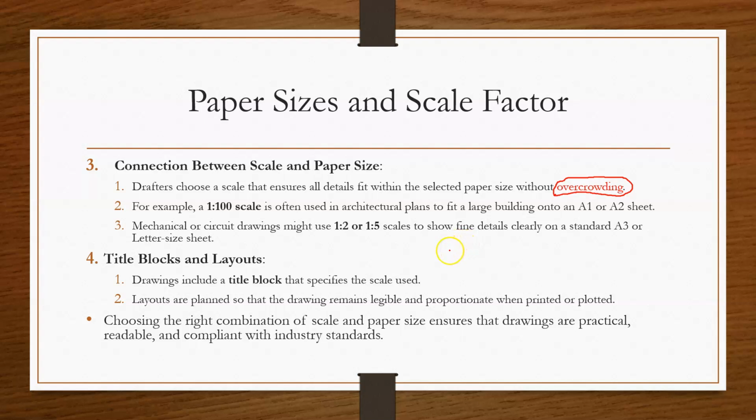Now that is also going to be where you're going to see the "not to scale" or the actual scale factor or anything of that nature sitting there. And I already kind of gave you a little hint there. If you see this on a drawing, just remember that that means not to scale, right? That is, I wouldn't say a bad thing, but it could be depending on what you're trying to do with the drawing. So if you see this on the drawing typically and something is missing, you're going to have to make a phone call, and I'll explain that a little bit later, right?